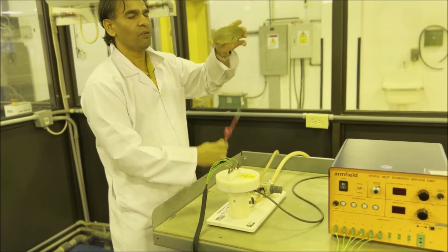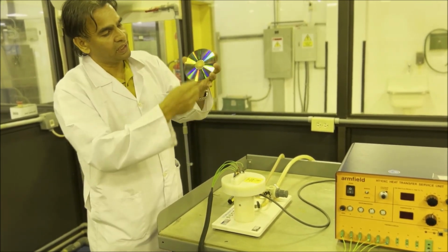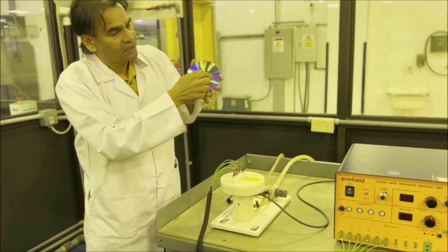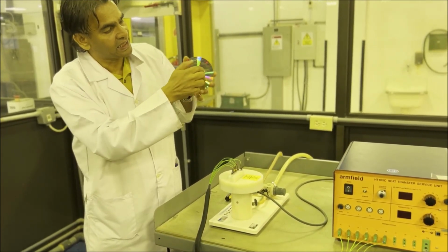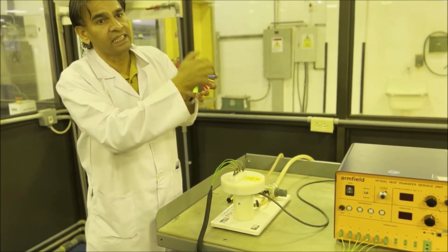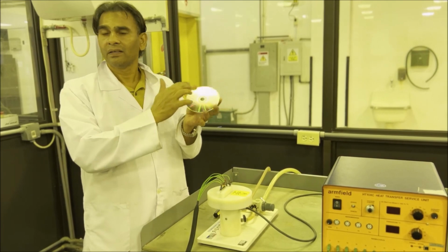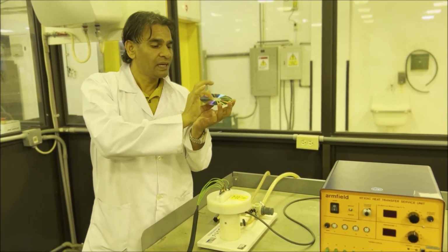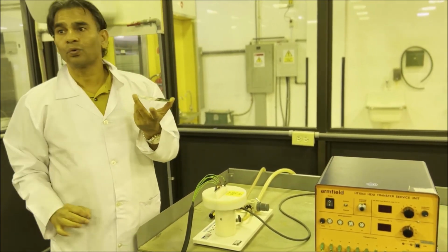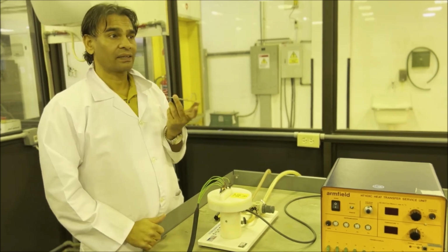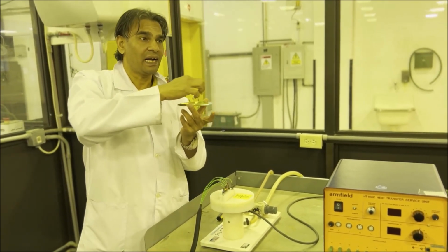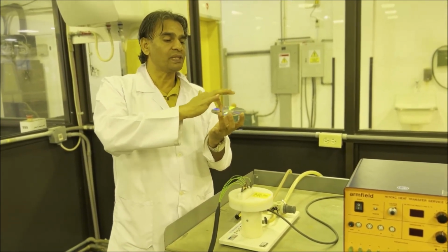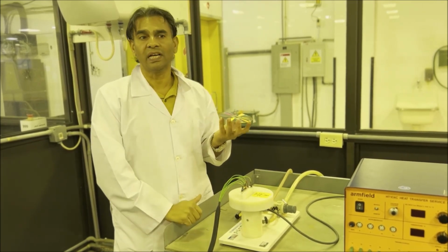Now heat will flow. How will heat flow? Along the radial direction, everywhere. If I consider this, the heat is flowing and this area is increased. What is the area? It is not a circular area, pi by 4 d square, no. It flows along the circumference, 2 pi R L. 2 pi R is the perimeter and length you can say is thickness. So area is going to change as R is going to change.